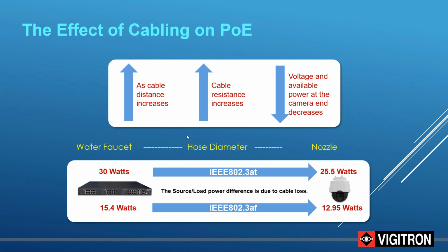And the goal is to transmit IP and PoE over coax cabling without the expense and sometimes even health conditions that are required for inspections in hospitals and schools if you have to remove that coax. Coax is very different from CAT cabling. Other applications might include what we call single pair cabling, mostly in alarm situations, and the requirement there would be to run IP or PoE over single pair cabling. Both of those, as an example, are not CAT cabling, and therefore they have different characteristics.